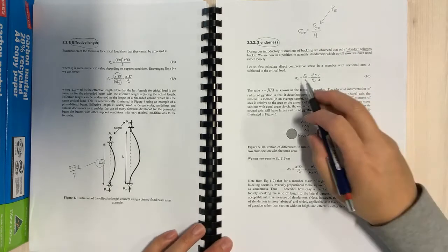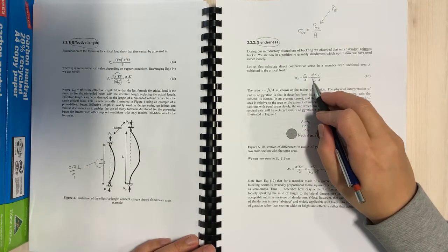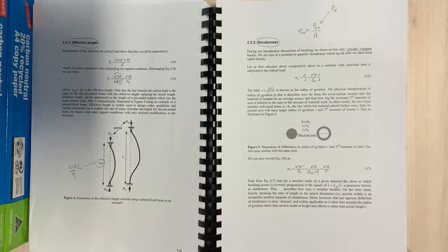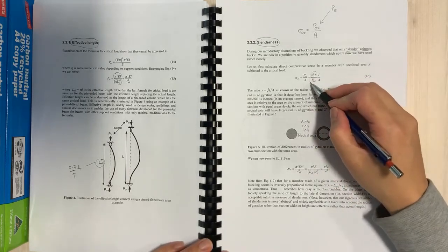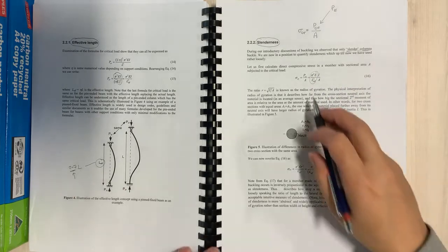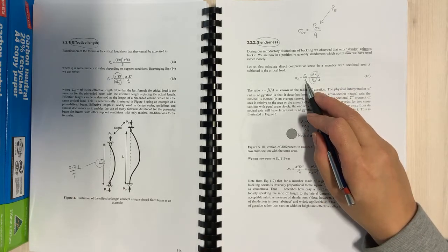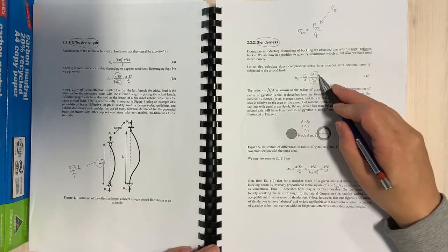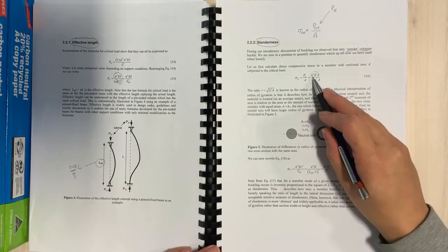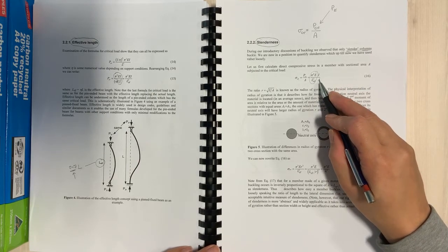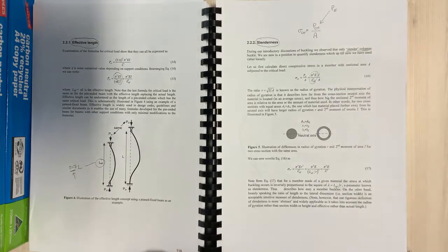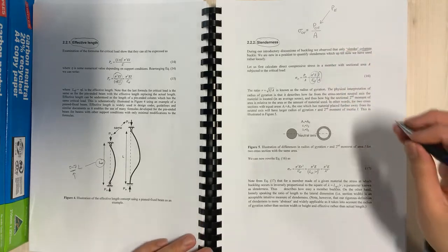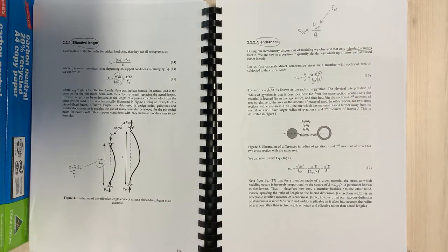So from there, we put pi squared EI over L effective squared, recognizing now that we're thinking in terms of effective lengths, so that everything can be related back to the same expression. And then we've divided it by the area, and we can see that our stress now has an I over A. Now, this ratio, I over A, is known as the radius of gyration.